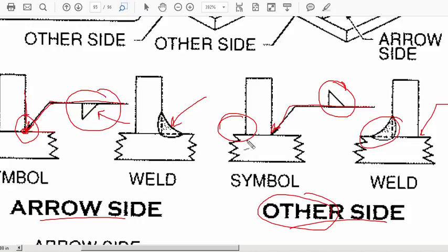That's one of the crucial things to understand with weld symbols, is the fact that there is above and below the reference line means it may not occur where the arrow points. A lot of times it would be great if all drawings had it where the arrow just touched where you're going to weld and that was it. But the fact is, it's just not the case. Sometimes you have to really pay attention to, is the weld going to be over here, even though the actual arrow is in one of the places.